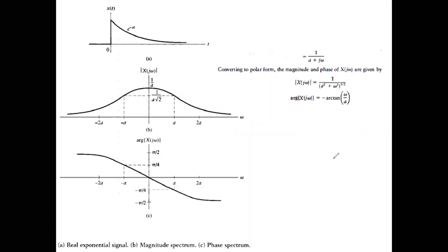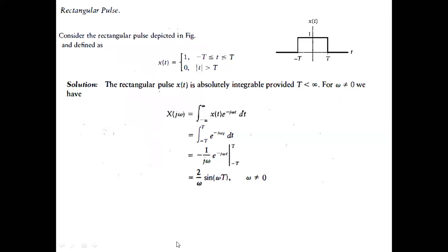What is the next standard signal? Yes, it is the rectangular pulse. Can you guess what is the answer for the rectangular pulse? Usually, whether it is continuous or discrete, the Fourier transform of a rectangular pulse is a sinc, and the Fourier transform of a sinc is a rectangle. So here is a standard signal once again with some minus T and plus T. If it is minus 4, then you substitute a 4 here, minus 4 to plus 4. Remember, all these numericals are like formulas which we may use as ready results as and when the situation arises.